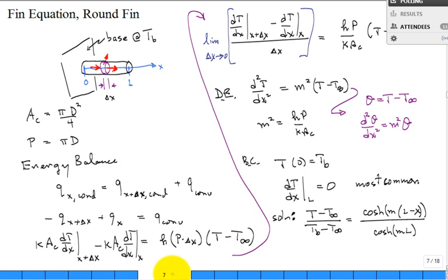Now let's get to that mathematical equation, and then we can get to our hyperbolic stuff, our hyperbolic cosine and hyperbolic tangent, right? Well, you have to set up from an energy balance and establish a governing differential equation. Start with a little control volume, shown here in purple. You have conduction and convection. So there's the 1 in and 2 outs.